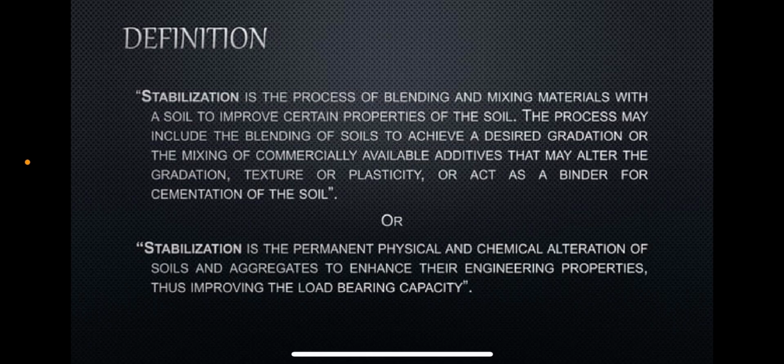And the definition: stabilization is the process of blending and mixing materials with the soil to improve certain properties of the soil. The process may include the blending of soils to achieve a desired gradation, or the mixing of commercially available additives that may alter the gradation, texture or plasticity, or act as a binder for cementation of the soil. Stabilization is the permanent physical or chemical alteration of the soil and aggregates to enhance their engineering properties, thus improving